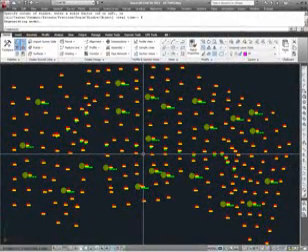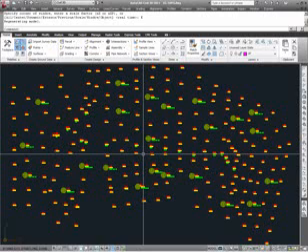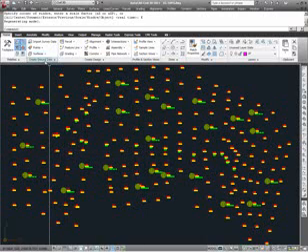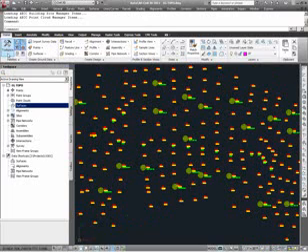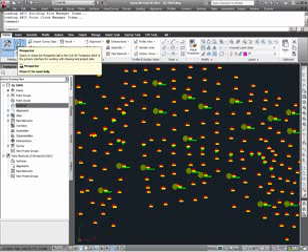The purpose of this video is to provide a brief demonstration on the process of creating a Civil 3D surface model. As we get started, the first thing we will need is the Prospector view from the tool space. If this needs to be turned on, it can be accessed via the Home ribbon tab, and under the palettes we have Tool Space. Clicking on the tool space, the view is enabled, and if you do not see Prospector as one of the tabs, Prospector may be turned on via the Prospector tab here.